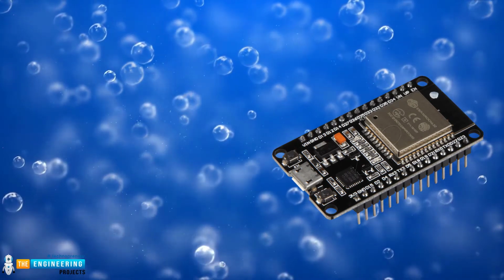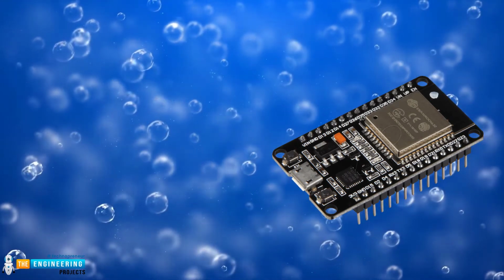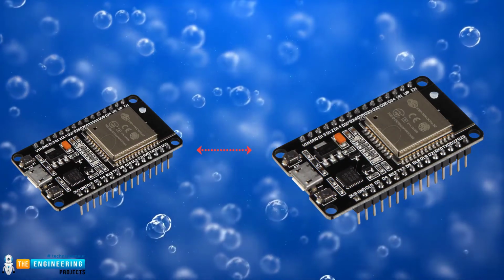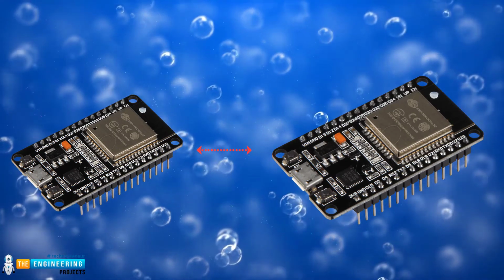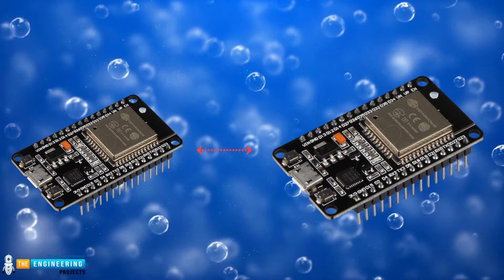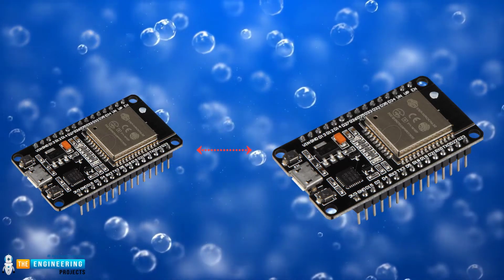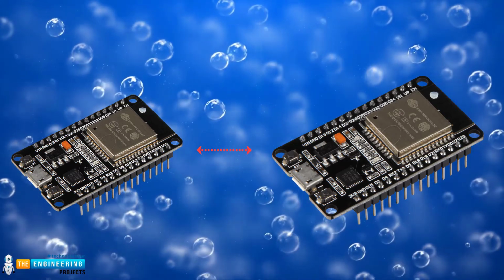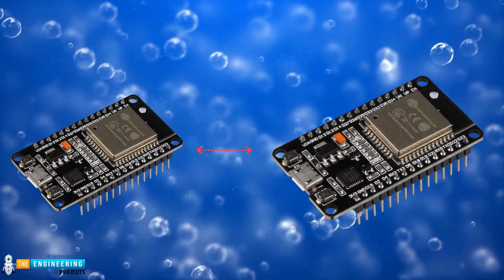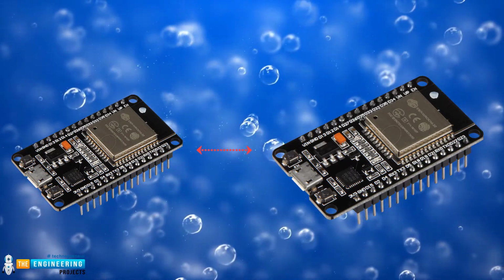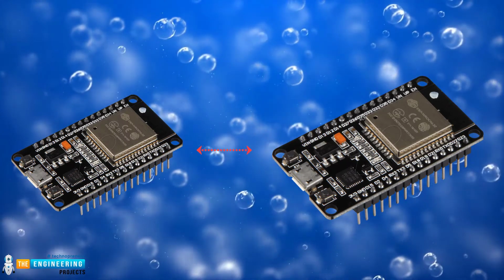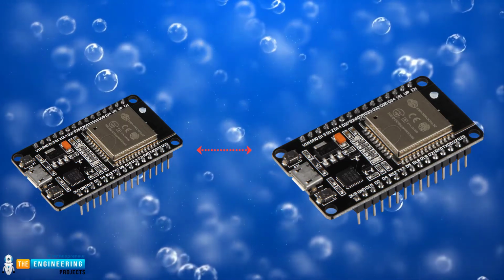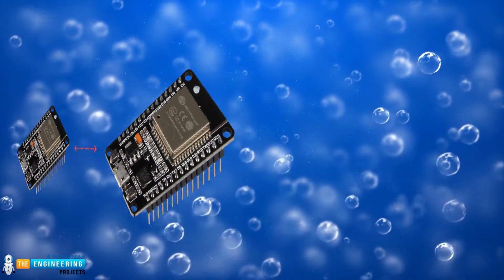For simplicity, we can say that the GATT server defines the format in which two or more BLE devices can communicate with each other. GATT server offers some services like heart rate services, battery services, and some information services. And each service further offers some properties like read, write, notify, and indicate. We can enable or use any of these services or properties as per our requirements. For identification purposes, a unique ID or UUID is provided for every service and property.